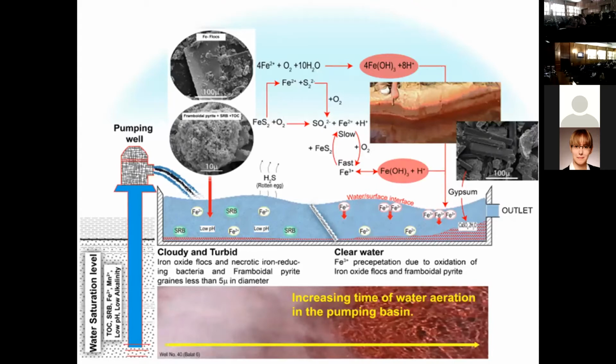Some wells have bacteria like SRB bacteria and some other salts like iron sulfide that, when they precipitate on the membrane, destroy it and decrease its lifetime. We face this problem daily with companies working with wells having a high concentration of iron and manganese, also in Upper Egypt as discussed in this project.